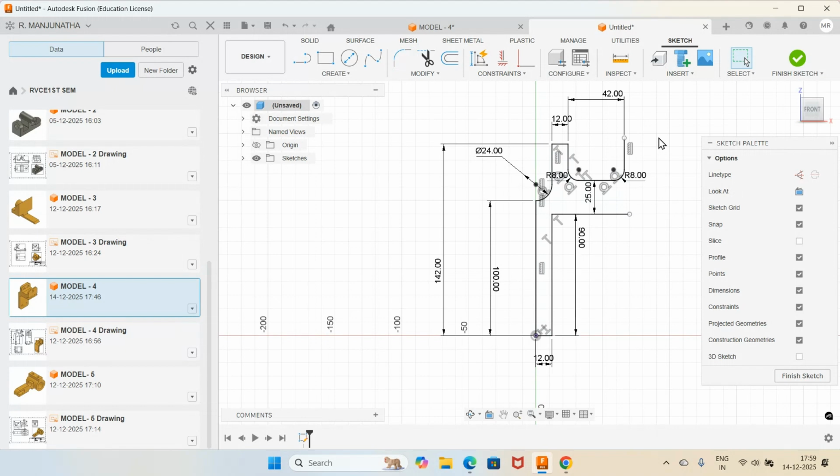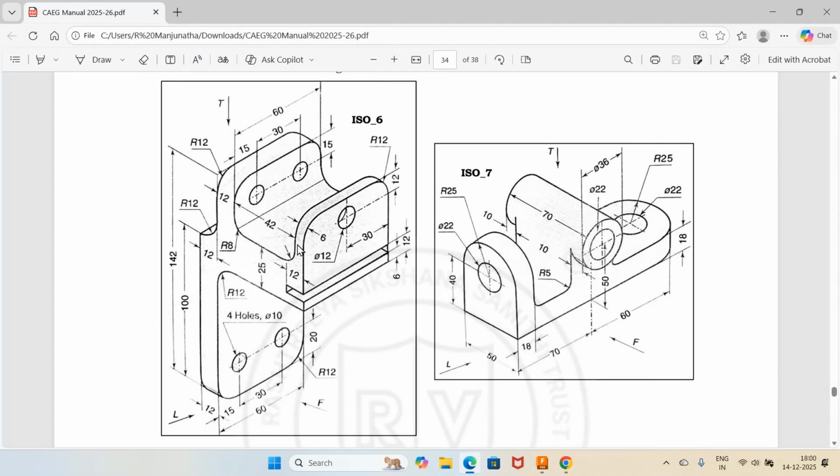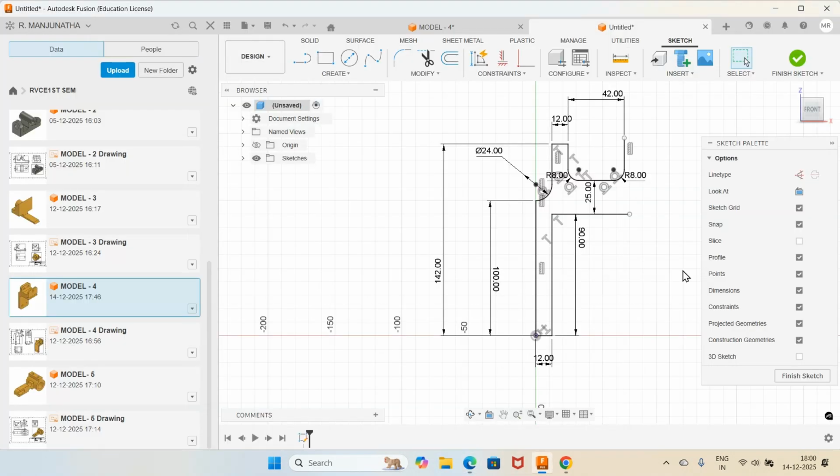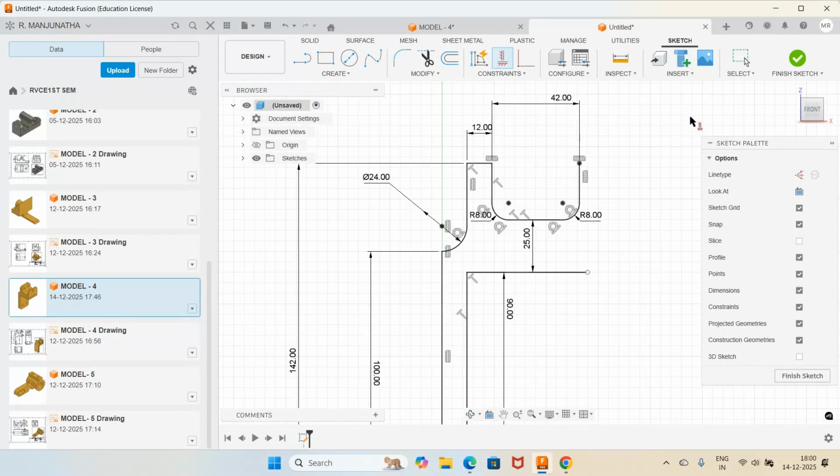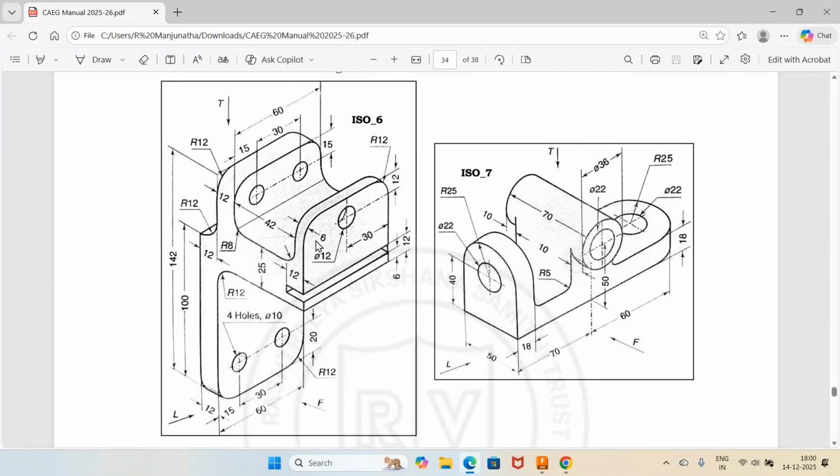Once you do that, now I have a thickness of 6 mm. So go to Line, select this, and go to Constraint, select this and this should be horizontal. Then go to Dimension, select this as 6. Then you come down directly to this point.